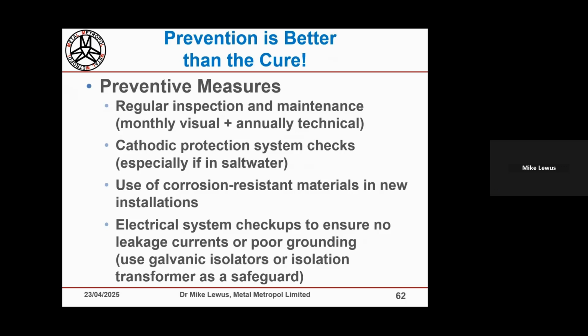One thing I would say is if it never had anodes on it and it's always been sat in fresh water, obviously that's not a very conductive electrolyte. And it could be quite possible, depending on the materials. I presume we're talking about things like bronze propellers or stainless steel prop shafts? Yes, and a stainless steel rudder. Well, depending on the nature of those grades, bronze is probably extremely resistant. Stainless steel, if it was at least 316, I wouldn't really expect that.